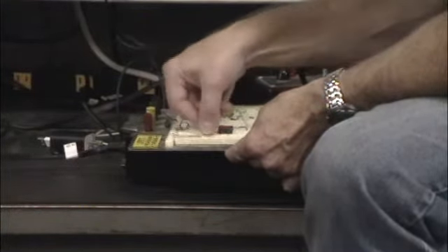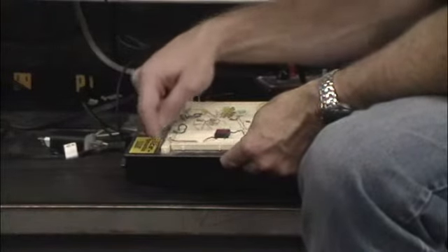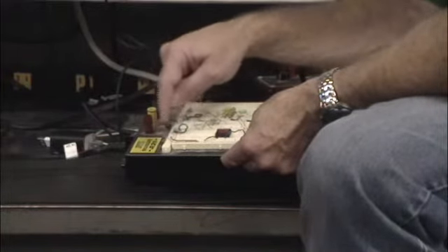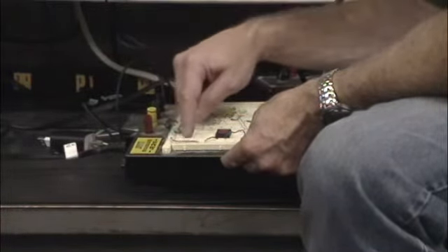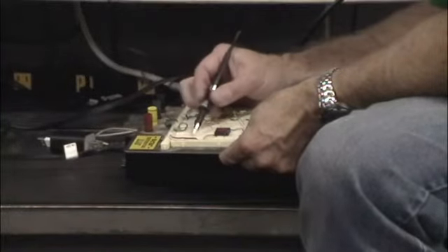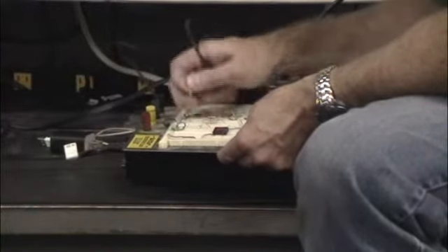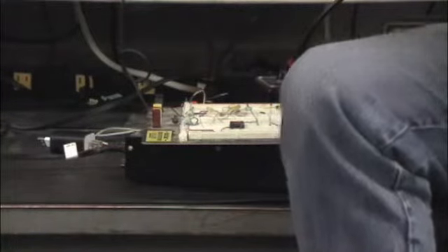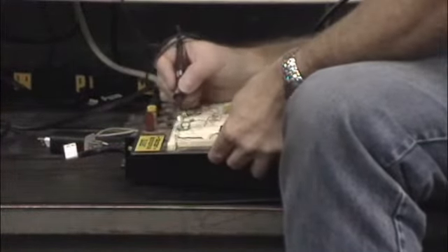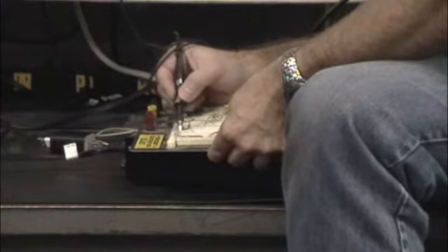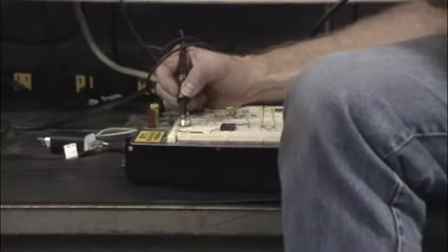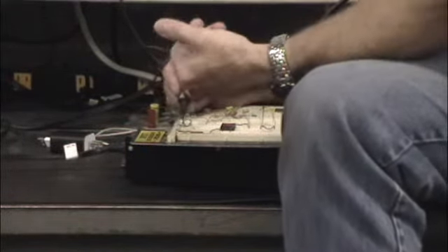So you have a red bar and a blue bar. And generally, the blue bar is connected all the way across, and the red bar is connected all the way across, but there's nothing connected this way. If you look at these little holes, they're press fit, so when you push something in, it's got little pieces of metal that are shaped like this, and when you push the pin in, it pushes them out of the way, but it holds it in place. So these 5, A, B, they're actually labeled up here at the top, A, B, C, D, E. They're connected. There's a little metal bar in there with a whole bunch of these little grippy tabs on it that connects them all in a line.